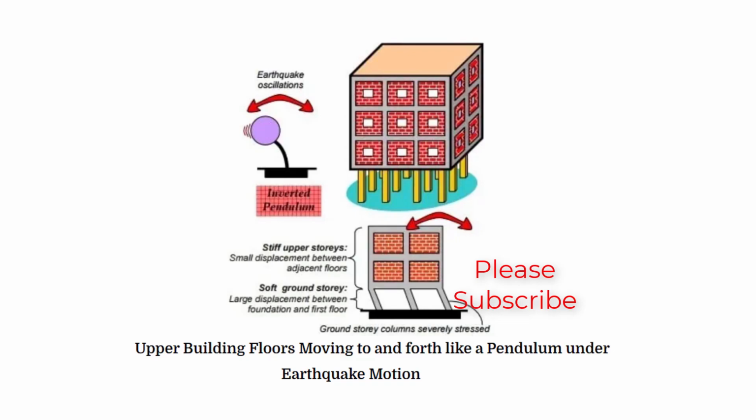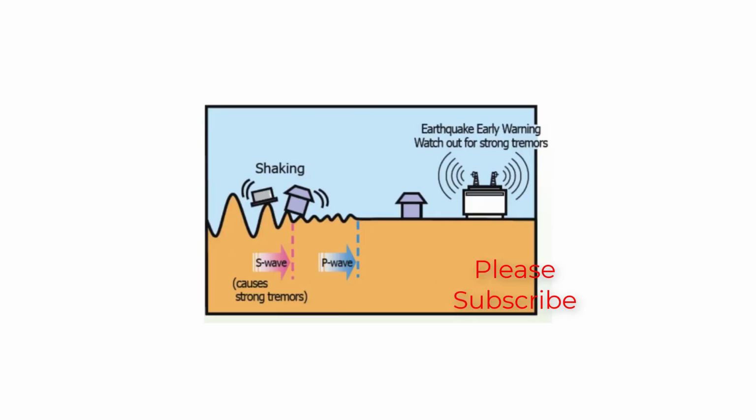So, if we see the overall reasons, we have seen that although the earthquake was very powerful, a few of the things could be controlled. Like, a few more research efforts are needed from the code committee, like revisiting the design spectrum curve, consideration of the aftershock effects, and so on. In addition to that, more advanced seismic warning stations are to be properly implemented.